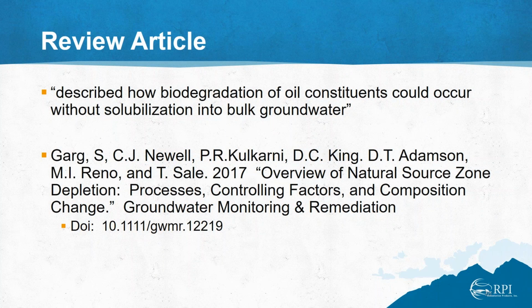Number one is, as people are probably aware, we use gypsum as a time-release source of terminal electron acceptor, of sulfate, over time. So that's one aspect of the sulfate. So when we did the treatment on these LNAPL sites, we put as much gypsum as we can in the ground. And then the other thing that we do is we prepare the slurries in a solution of either sodium or magnesium sulfate. So the sulfate concentrations are really high. We're talking thousands of ppm when we put those in the ground.